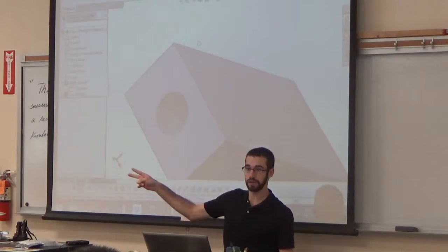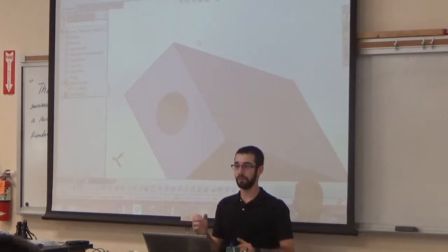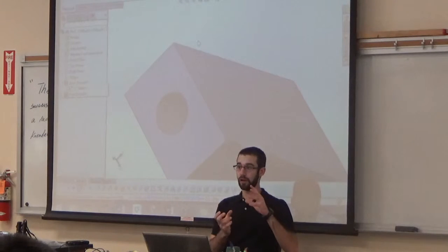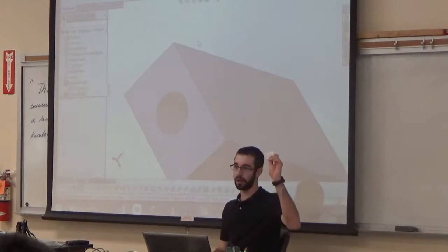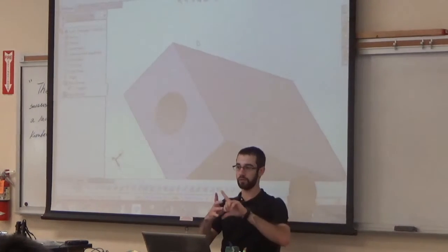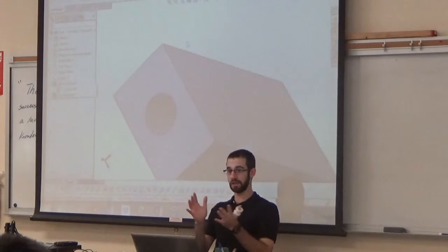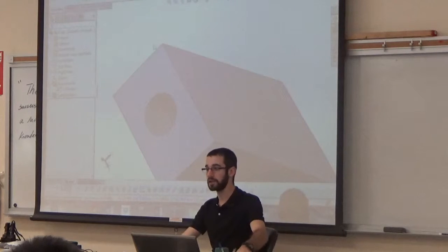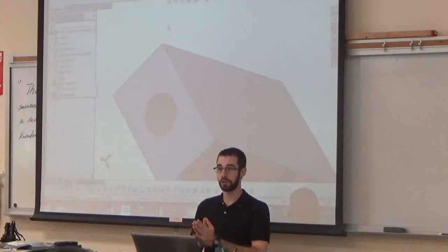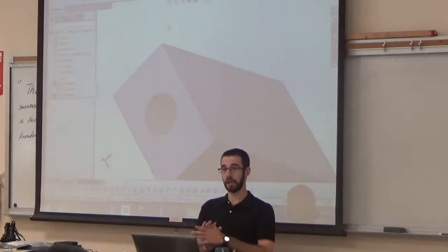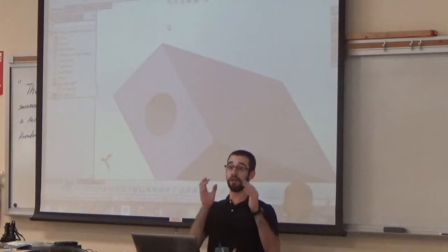So those are two processes. Another one, a big one for plastic parts is injection molding. And basically what you do is you do a cavity and you fill with plastic. So this is an injection molded part right here. I'll get to this in a little bit later. But you basically pump a lot of plastic into this mold. And the way you make sure that all those parts are the same, again, is the drawings. So drawings are very, very, very important in terms of product design and making sure that you have the right part. And in a lot of companies, there's a quality person or a quality section of that company that's basically what they do.